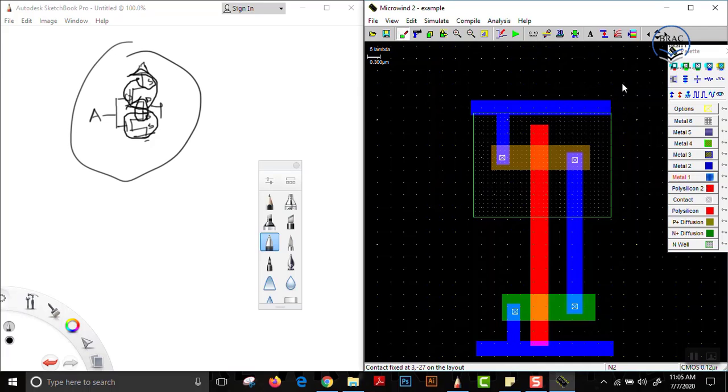Now what we need to do again is we need to connect. We can see here blue arrow, this is our VDD supply. We can connect VDD to this. This ground, we have ground supply, we can connect ground to this. Another thing is, this is our gate. In gate we input a clock signal. Here we have a clock. We can add a clock and connect it to this.